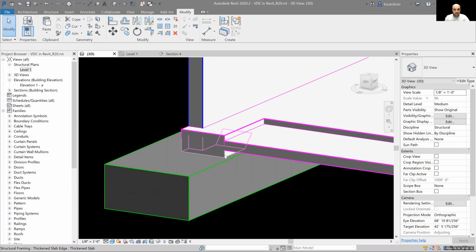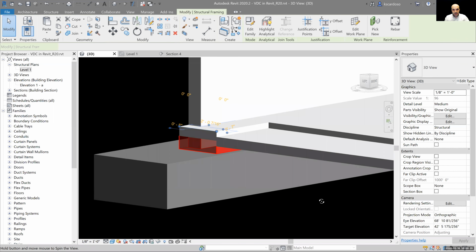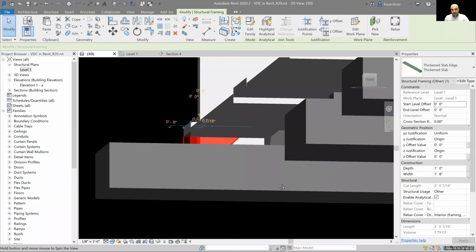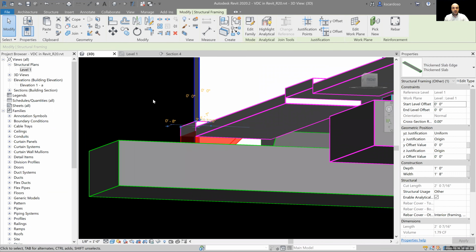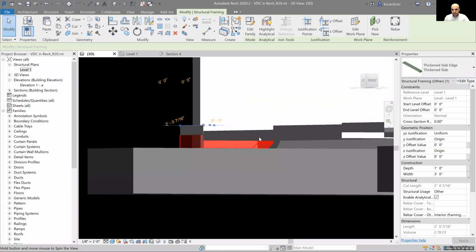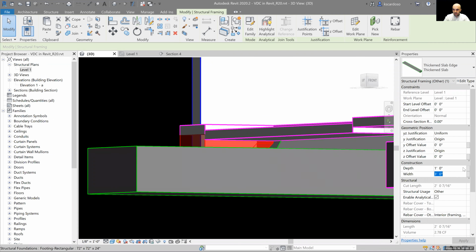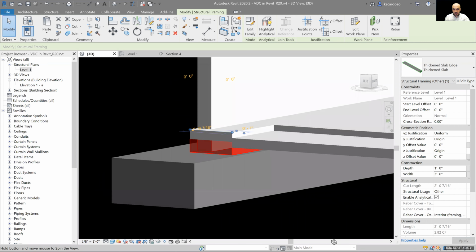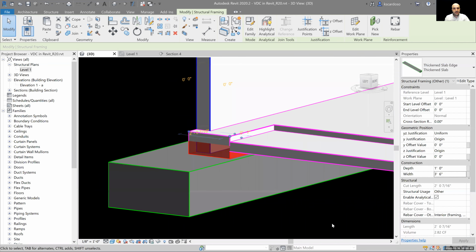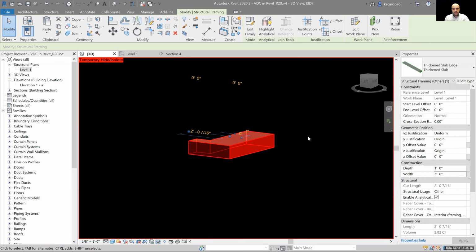Now if we select that beam and we look under, there's a little gap there. Well, this is where you don't have to worry about the math. You just make this width what it needs to be until that gap fills in. Let's go to 3 feet. Still no. You can see that there's a little angle in there. Let's keep adding. 3'6". All right, so it filled it in. And now let's go ahead and isolate just this family, IE.